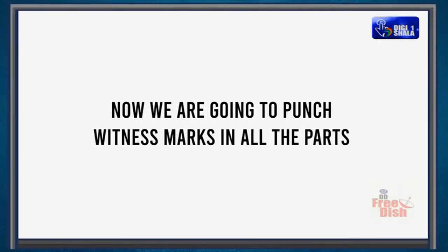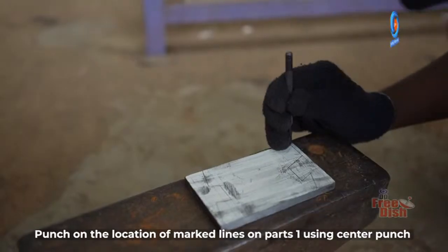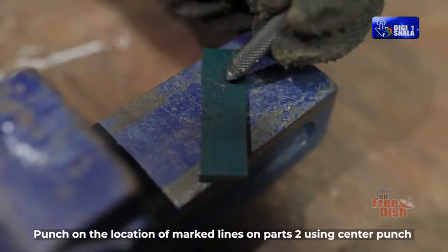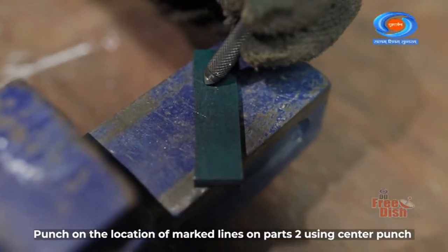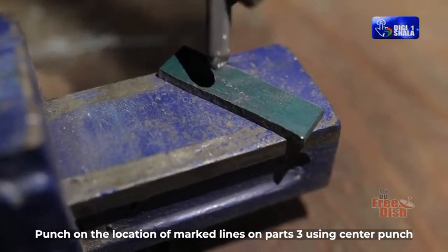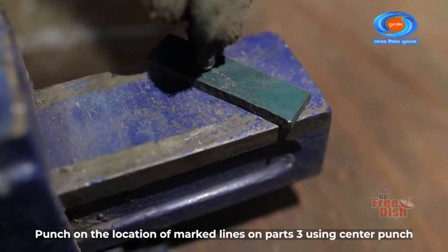Now, we are going to punch witness marks in all the parts. Punch on the location of marked lines on part 1 using center punch. Punch on the location of marked lines on part 2 using center punch. Punch on the location of marked lines on part 3 using center punch.